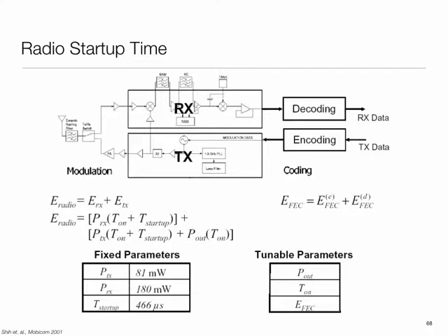In some radios it can be even worse because they may have to handshake with the base station, establish a connection before the data can go out. So if I'm sending data sporadically, then these startup costs can begin to dominate. For applications like sensors, where you're sending data rarely, it is quite necessary that the startup cost be kept very low. That is, I design radios which can wake up very rapidly, quickly send the data, go back to sleep. So all that handshaking should be kept to a minimum.